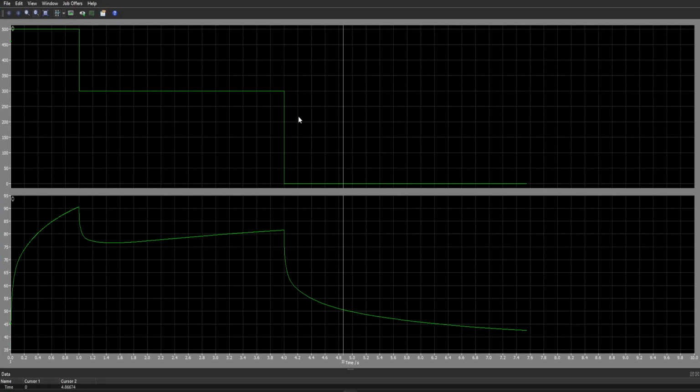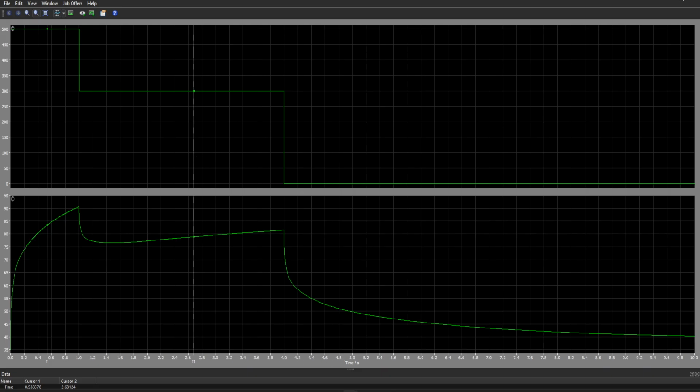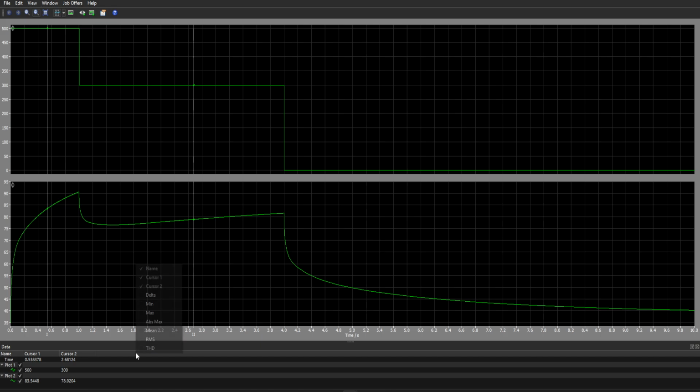After running the simulation again, now this looks good. This is what I was expecting as well. So at the beginning, you see the temperature was at 35 degrees Celsius. Then it follows that exponential curve to reach the peak point. Let's check the value here. Show the maximum. So within these two cases, we have a junction temperature of 90.61, which is exactly what we calculated theoretically.